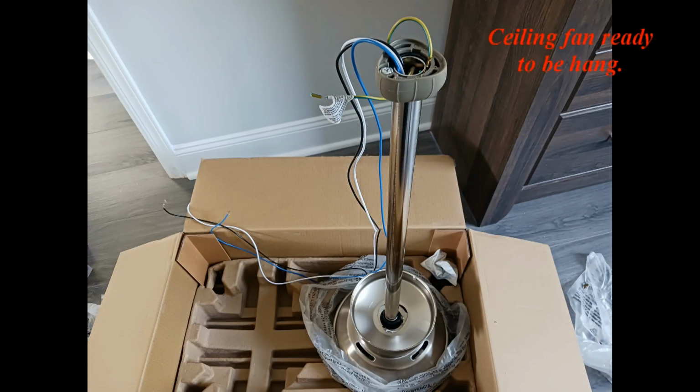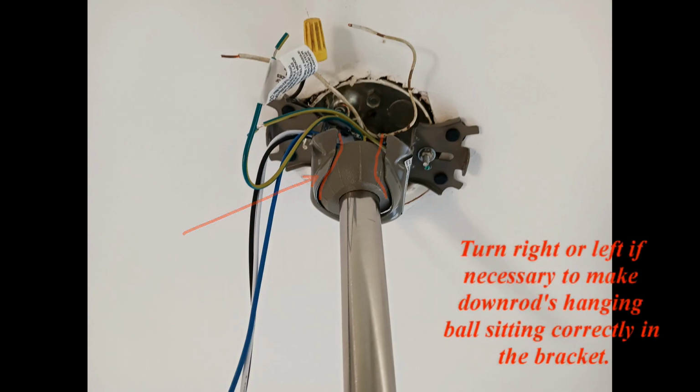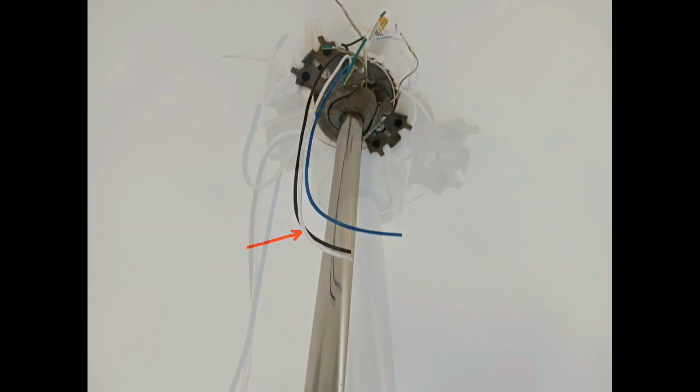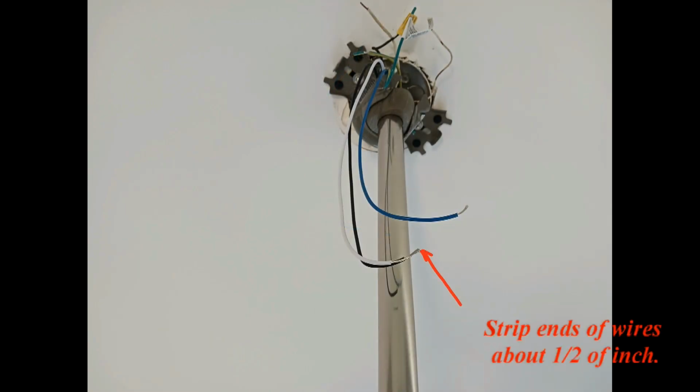Ceiling fan ready to be hung. Raise the fan and insert downrod's hanging ball into the bracket through the bracket opening. Turn right or left if necessary to make downrod's hanging ball sitting correctly in the bracket. Trim fan wires to desired length, not less than 6 inches. Strip ends of wires about 1/2 inch.